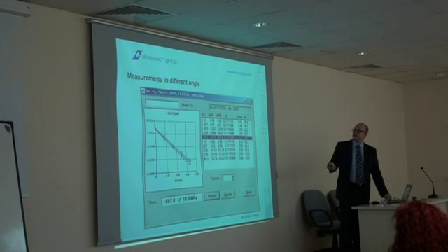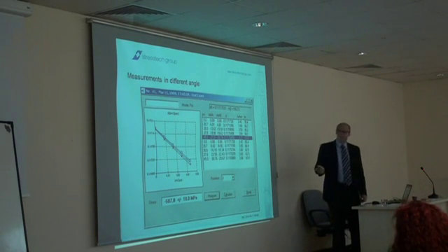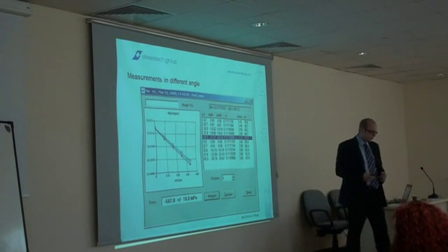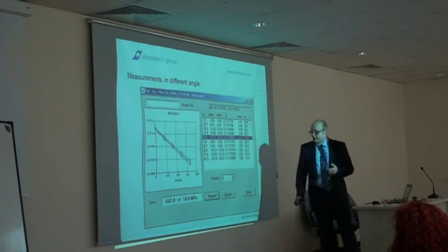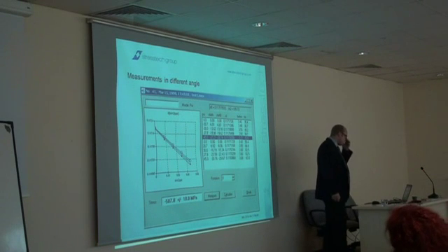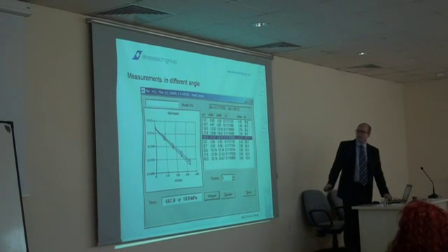And if, for example, our D value is 0.11733 at ψ angle 45, it means that the planes go like this, and it automatically means that we have a tensile stress in our sample. And actually, what we need behind this calculation is to know the material parameters, Young's modulus and Poisson's ratio. And if you don't know those values, it is also possible to measure them with a four-point bending device, an elastic constant device.